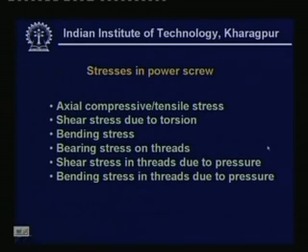Now, all of the stresses due to these last three criteria must be taken care of, and we will have to find out the equivalent stress. When you use the von Mises criterion you will have to find out the equivalent normal stress, or if you want to use maximum shear stress then you will have to calculate the maximum shear stress. Everything depends upon the state of stress at different points.